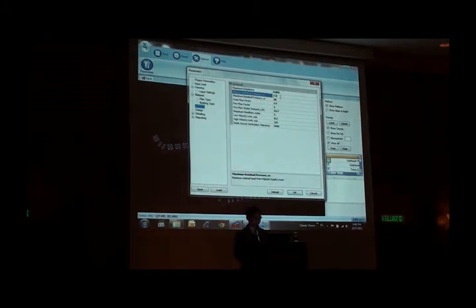You can see the minimum residual pressure 7.5. It means less than 7.5, the software will say fail. More than 7.5, if more than 30, the software also will say fail. So if you want to have a pass result, that means must be within 7.5 to 30. But you can set here. Okay. Then the peak flow factor and the fire flow factor. This one very standard, 2.5 and 1. Then the fire flow water demand, you can set also. Then the rest is head loss and the velocity setting.